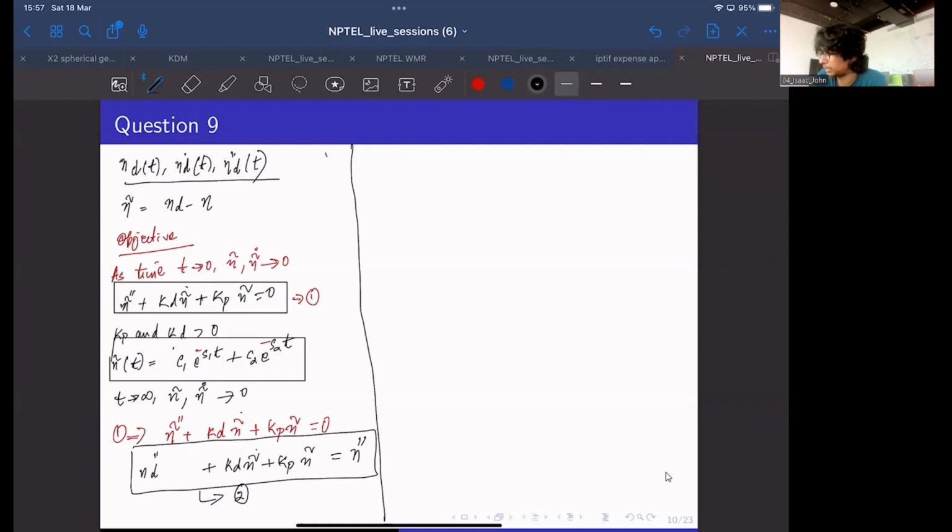Okay, I'm reproducing some equations from robot dynamics. Robot dynamics basically says the torque of the robot is equal to the mass matrix D of zeta times zeta desired double dot plus N of zeta, zeta desired dot.